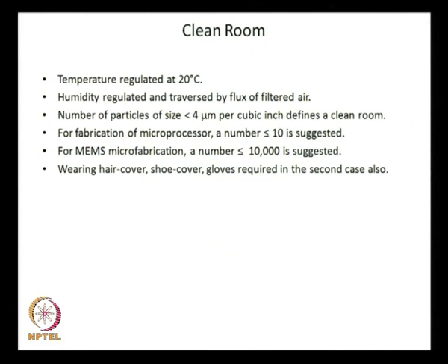The number given for a clean room, if it is less than 10, is typically suggested for fabrication of a microprocessor, whereas for MEMS microfabrication a number less than 10,000 is suggested. And if it is less than 10,000, typically wearing hair cover, shoe cover, gloves, etc. are required.